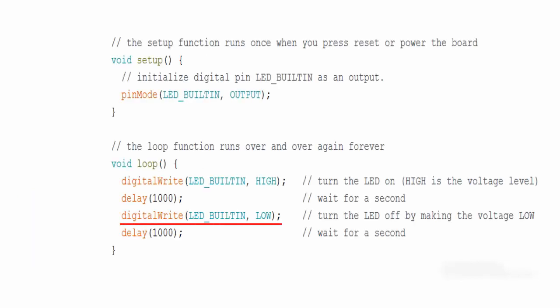Next, the digitalWrite function is called with the delay function, which turns the LED off for 1 second. This is still part of the process and output steps. Turning the LED off is just as much a display process as turning it on. Once the delay function is finished, the closing brace of the loop function is read. However, because loop establishes what is called a program loop, program execution returns back to the first statement in the loop and performs a second pass through the loop starting with digitalWrite again. This turns the LED back on.